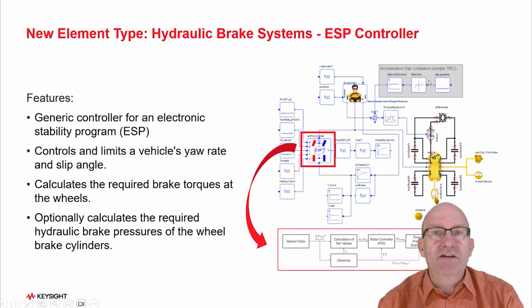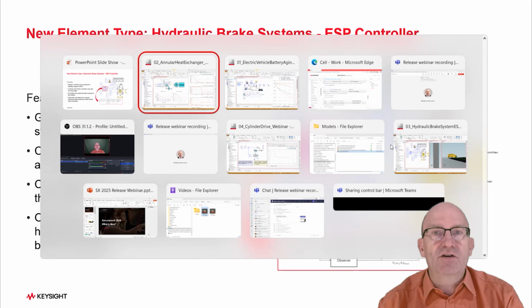The model we see here in the screenshot is actually just one which is using friction elements in representation of the brakes. So it's very strongly focusing on the dynamics of the vehicle, not so much on the internal structure of the component, the braking system. But I could exchange this with a more detailed braking system using the same controller and providing it with hydraulic pressures instead of brake torques. That's again something which I would like to show you in action.